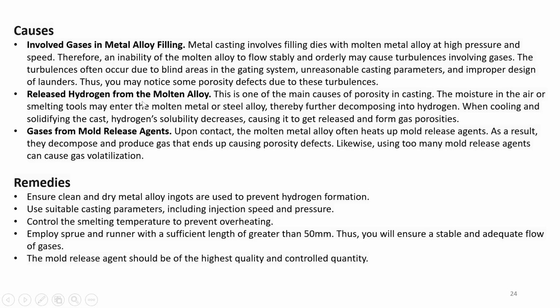Now the causes. First is involved gases in metal alloy filling. Metal casting involves filling dies with the molten metal alloy at high pressure and speed. Therefore, an inability of the molten alloy to flow stably and orderly may cause turbulence involving gases, and the turbulences often occur due to the blind areas in the gating system, unreasonable casting parameters and improper design of this gating system. Thus, you may notice some porosity defects due to the turbulences.